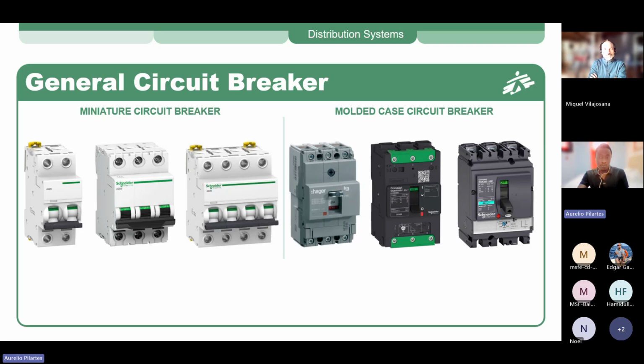And then you will be interested in having one MCB and setting it to a smaller current. They can have small currents, but not that small, because they have a defined range, and this range doesn't go down to values like 6, 16, or 20 amps. They could be from 100 to 150, from 80 to, I don't know, 200, depending on the specific model. But yes, they can also come below 100 without getting much lower. So in one of the cases, we use these MCBs because of the cross section of the cable we are connecting. Exactly.